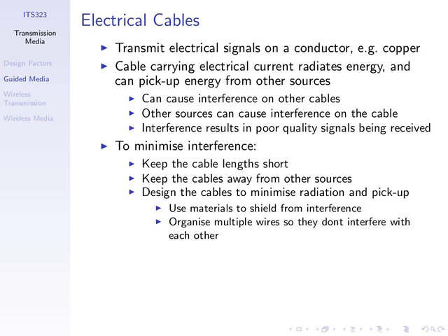So if we've got our cable, inside there are some copper wires, and we transmit our signal across those wires. The first problem is that some of that energy radiates out and can interfere with other transmissions. Similarly, we can pick up energy coming from other transmissions. And that causes the interference. Keeping the cable short can minimise the amount of interference, but that's against our goal of increasing the distance. We said in the first or second slide we want to maximise the distance.